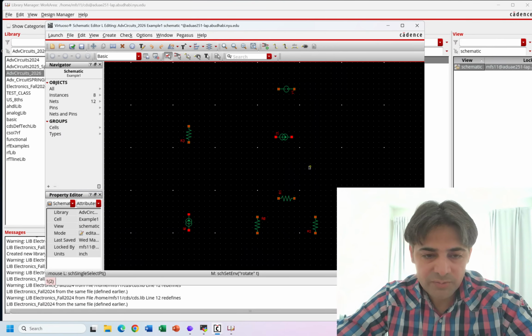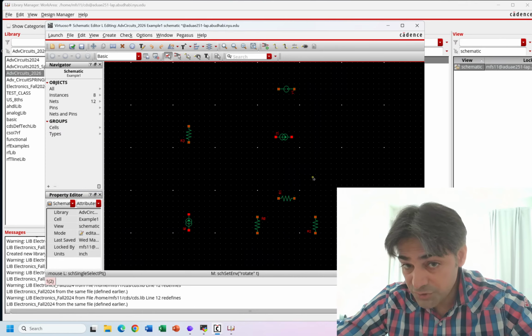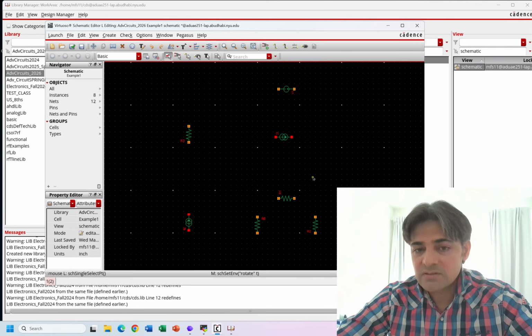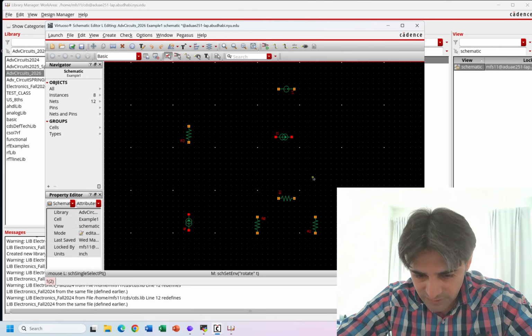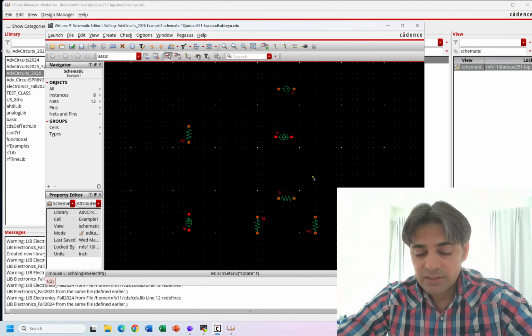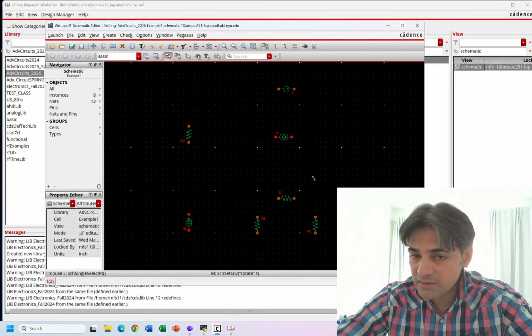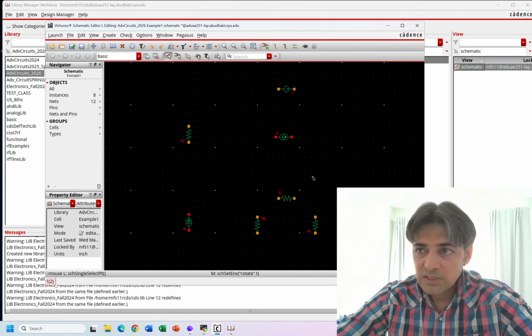So now we have pretty much all the schematic. The only last thing missing, without which your circuit is not complete and you're not going to get any points if you forget that, is the ground. Ground sets the reference for measuring all the voltages and currents in the circuit. So we have to make sure that the ground is always there. You might not see it in the schematics when you're solving your book problems, because the node with the highest branches is considered as the ground.